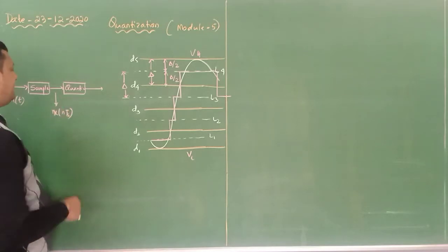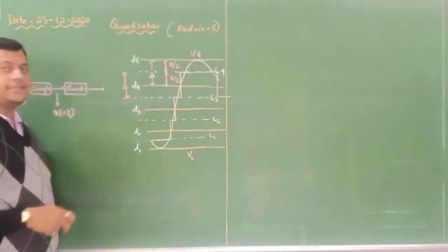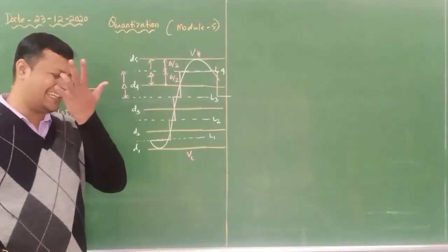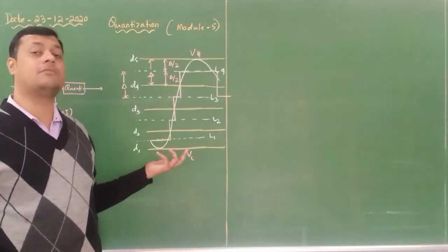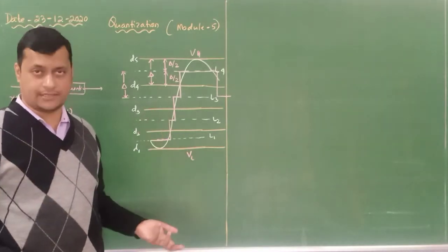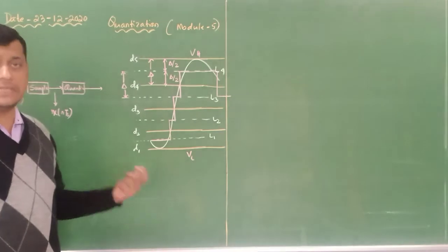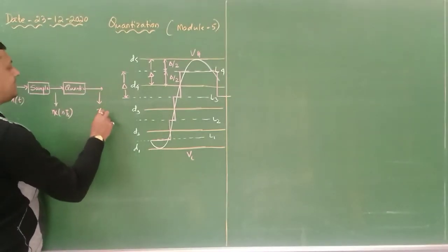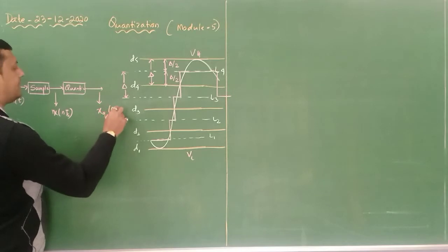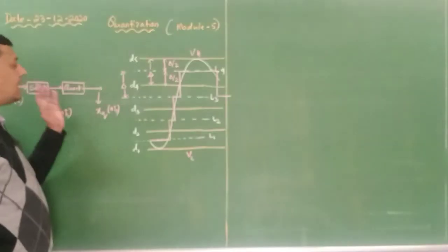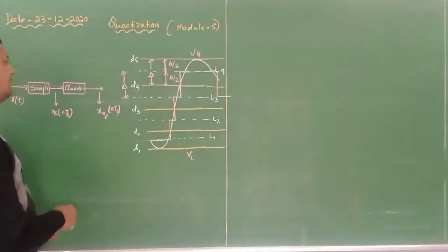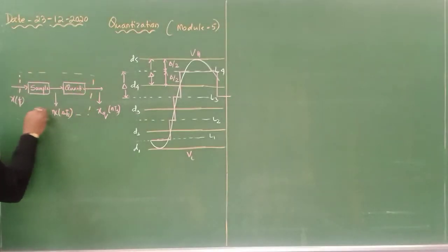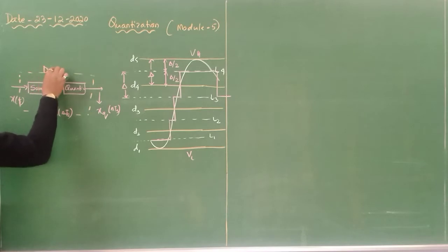And the sampled signal is either a natural sample or a flat top sample, or if it is instantaneous, there is no need to quantize, it is quantized already. We only have to identify the levels. So this quantizer's resultant is x cap of n. Done. So this is the output of the quantizer. Now if I consider these two steps together, these two steps are called discretization.